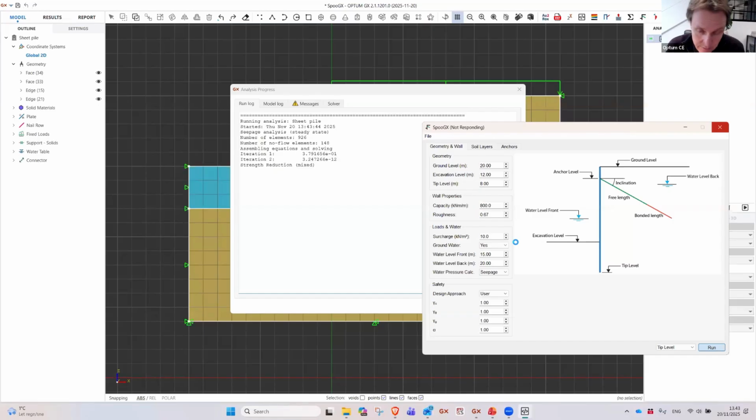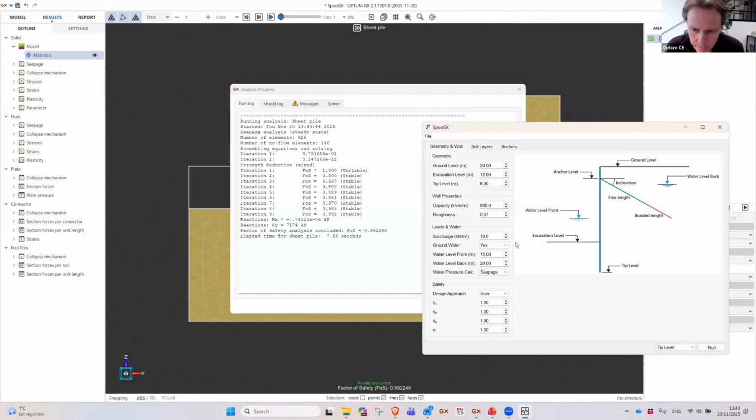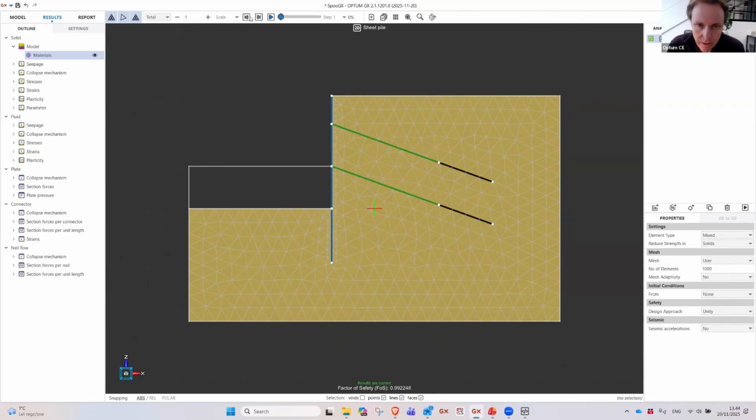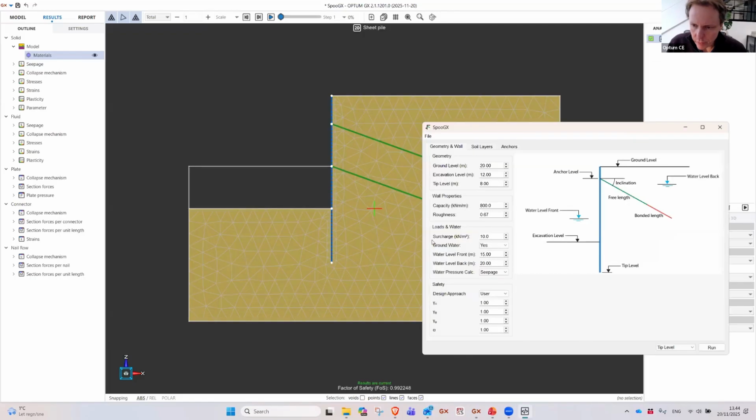That decreased too much, I guess, so now it will have to increase a little bit again. So yeah, it stops. There's a tolerance, I think, of 0.01. It stops when it's within 0.01 of a factor of safety of 1, which in this case was slightly below 1. So it is entirely possible to create these apps.